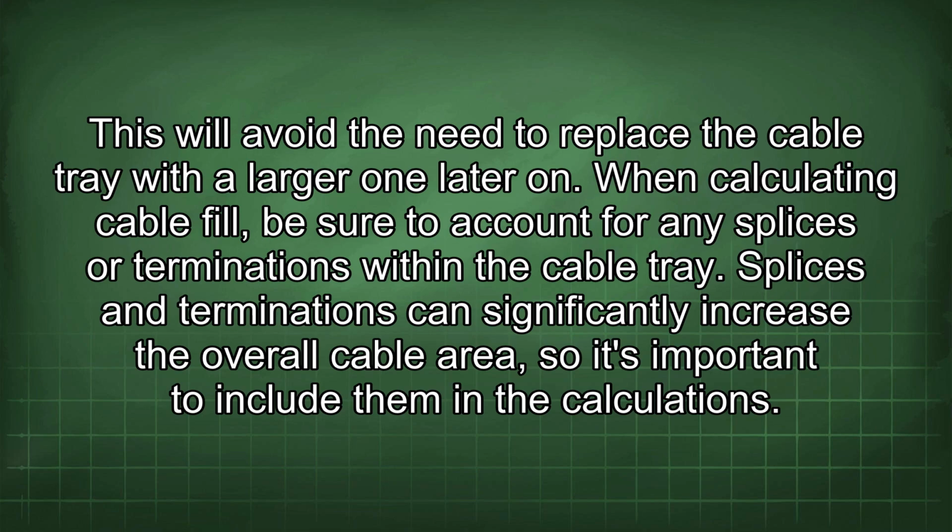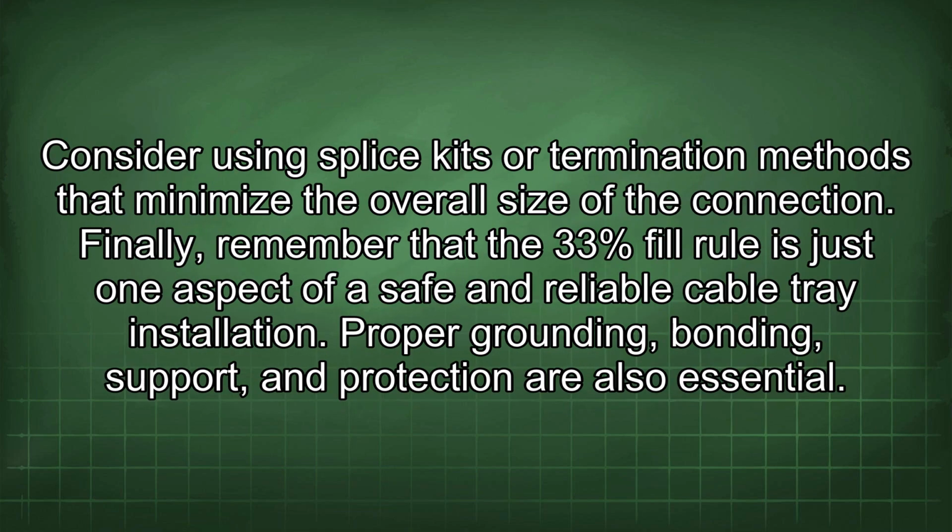When calculating cable fill, be sure to account for any splices or terminations within the cable tray. Splices and terminations can significantly increase the overall cable area, so it's important to include them in the calculations. Consider using splice kits or termination methods that minimize the overall size of the connection.